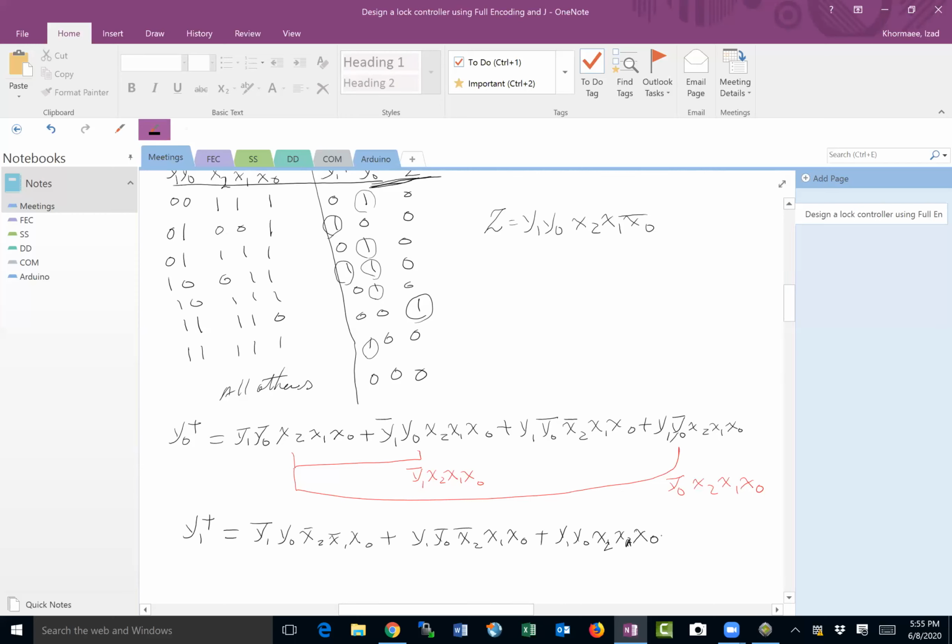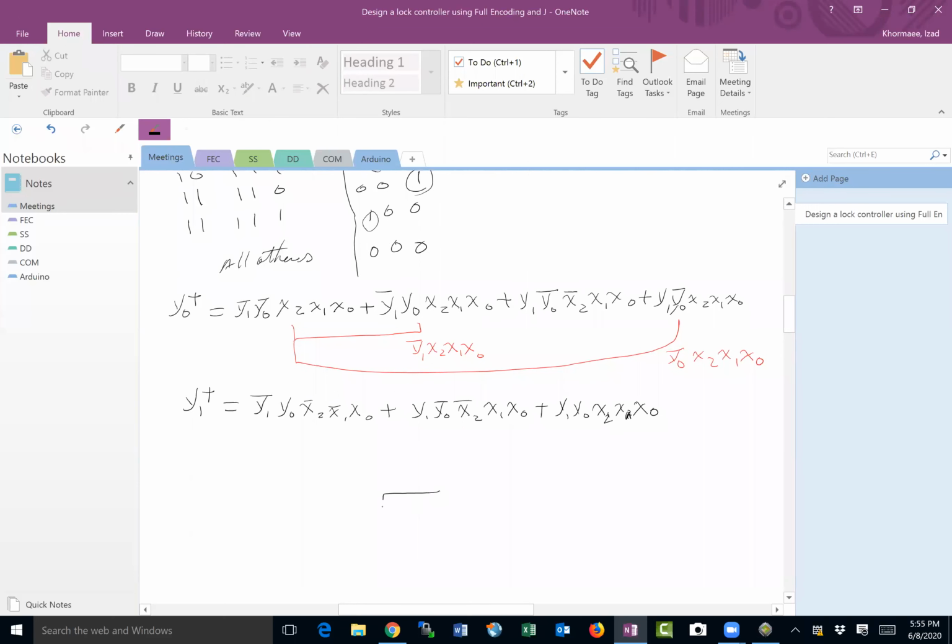So once you have this, the D flip-flop basically would be, boom, there it is. You have your x0, x1, and x2 coming in, and you have 2 flip-flops. If they're D flip-flops, Y plus is equal to D. You're done. These equations are the D equations. For a JK flip-flop, all you do is run your Y0 plus, if this is J0, K0, and do this.